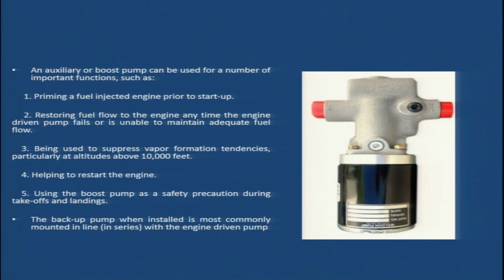An auxiliary or boost pump can be used for a number of important functions. This electrical pump has various purposes. It is used to prime a fuel injected engine prior to startup, so it is acting as a primer also. In engines which are installed with a fuel injector, this auxiliary pump is used to prime the engine.